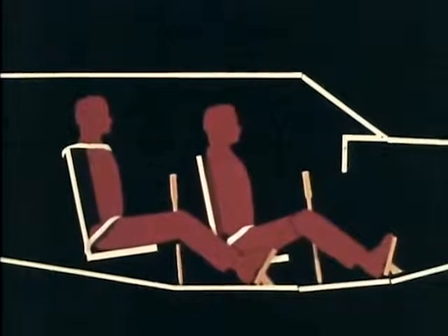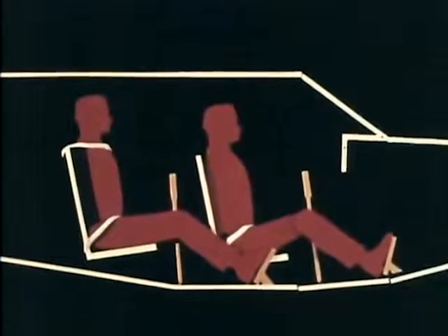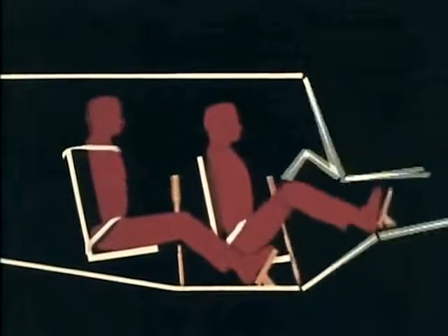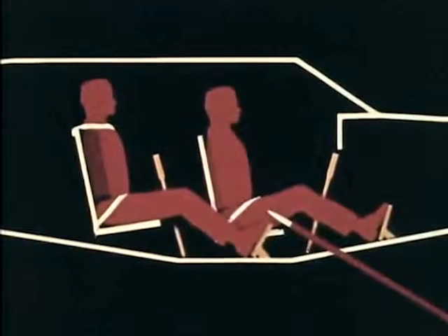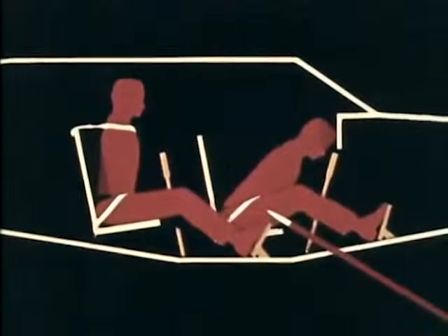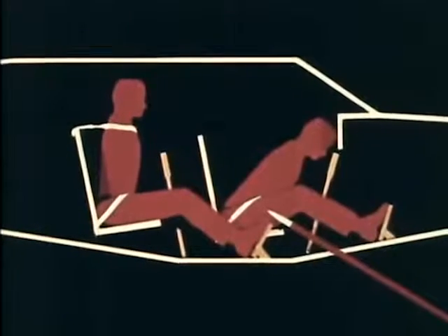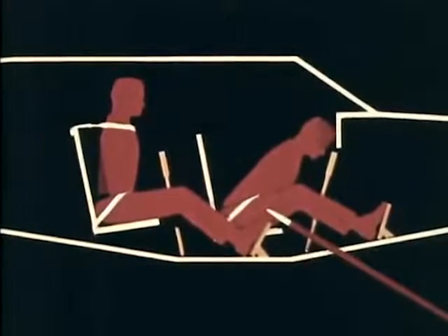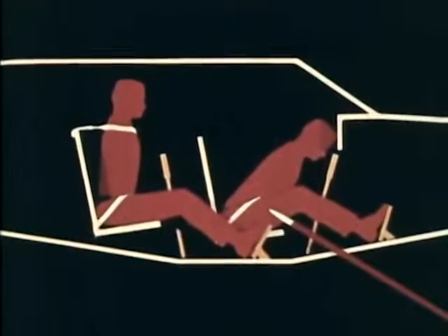To summarize, the information presented so far has shown that injuries in crashes result, 1, when the cockpit collapses and the occupant is crushed by the airplane structure. 2, when the seatbelt and shoulder harness stretch excessively under the crash loads. And 3, when the occupant is restrained by only a seatbelt. Even if the structure remains intact, both seatbelt and shoulder harness are necessary in small cockpits if serious body blows are to be avoided. The information presented here has also indicated the loads produced in the restraining harness during a crash.